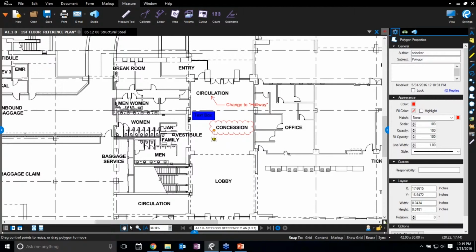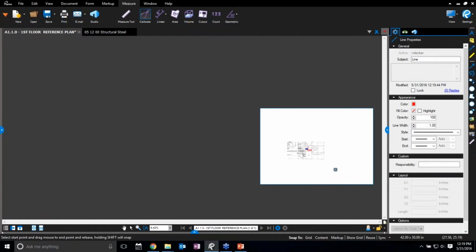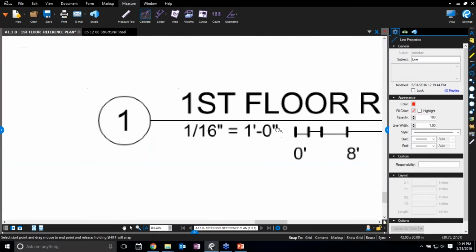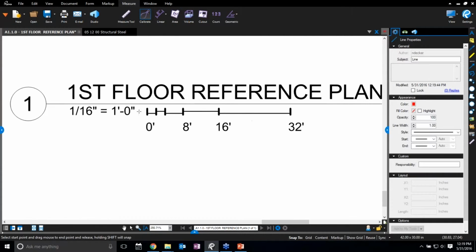The other item down the command bar line is the measurement function, which, just like any other markups, will place information on the page, basically floating above the content itself. But what's different about the measurement tab is that it's going to give me some sort of quantifiable information at the end of it. So, for example, in this case, I'm going to go ahead and calibrate this drawing, basically tell the computer what the scale of the drawing is, which in this case is 1/16 inch equals a foot. And so I actually have a defined scale here with known points in between.